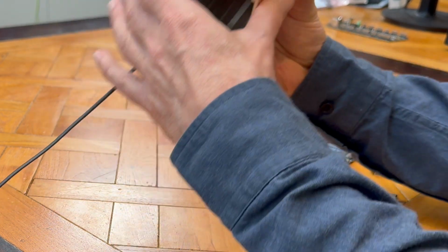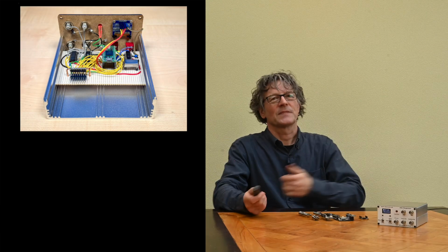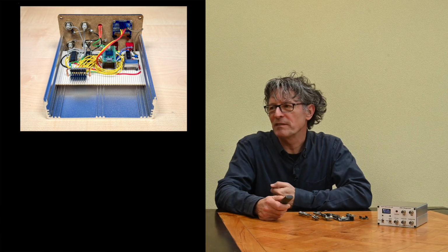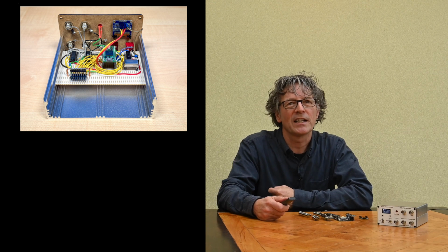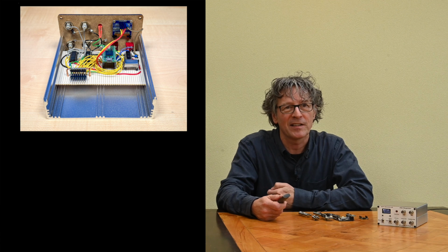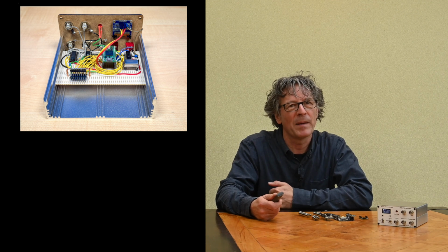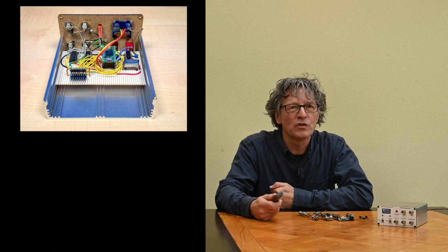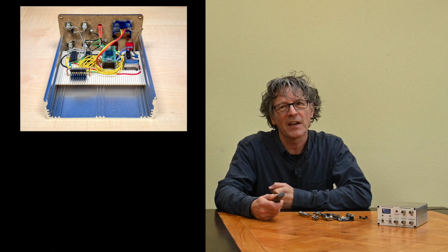And then if we move to the inside of the device, it looks pretty straightforward. It's not a very complicated design. You probably already recognize the MCU. You see a crystal, a 1 megahertz crystal that we divide by 10. That's the chip right above it. And we see a couple of other chips, which are basically the flip-flop memory and a buffer stage. And you might also notice at the left bottom there is an additional header there.